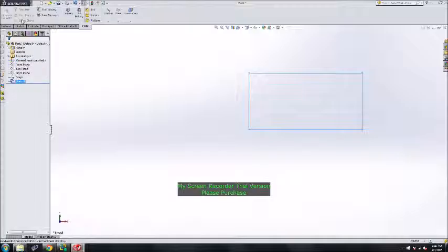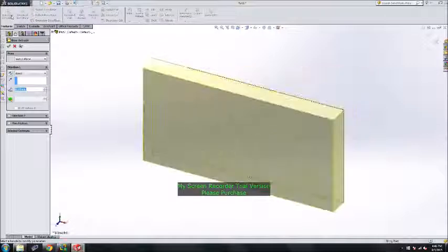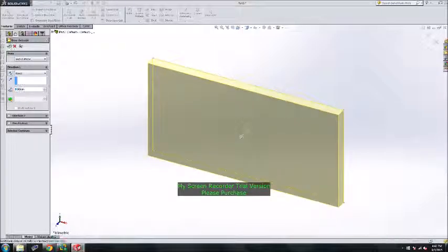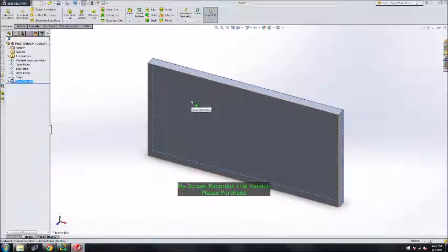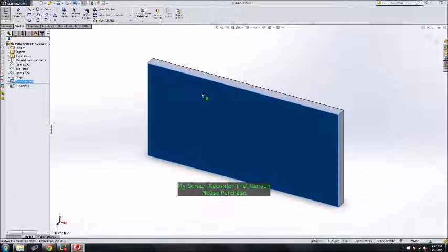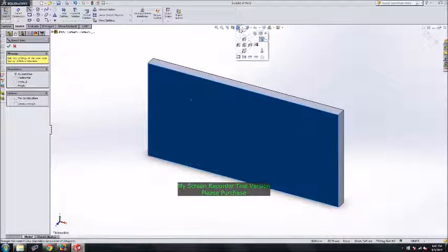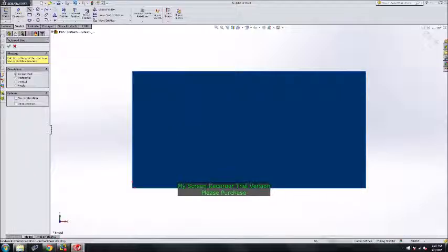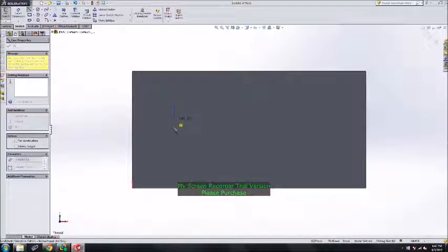Give the depth. For that, select the extruded base of width 5 mm. Once that is done, let's start sketching on the plane. Since we are going to make an H-shaped channel, let's start sketching the same. In today's case, I'm again selecting random dimensions. You can always put whatever dimensions you are required to make the channel.